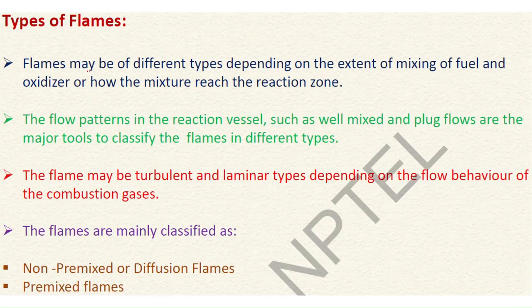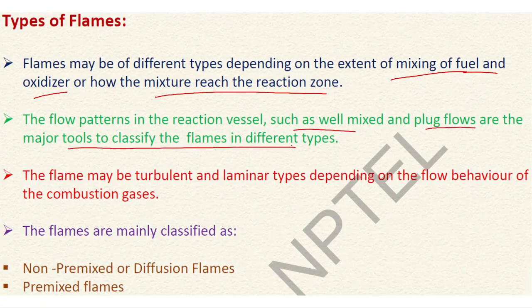Types of flames. Flames may be of different types depending on the extent of mixing of the fuel and oxidizer, and sometimes how the mixture reached the reaction zone. The flow pattern in the reaction vessel, such as well mixed and plug flow, are the major tools to classify the flame into different types.